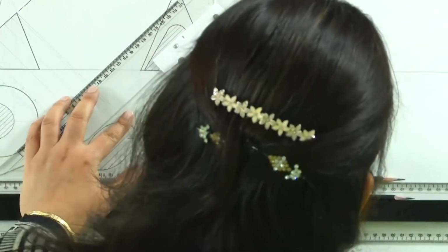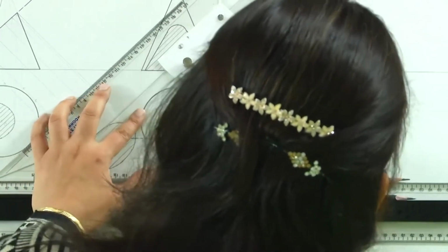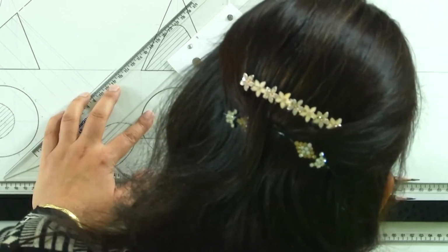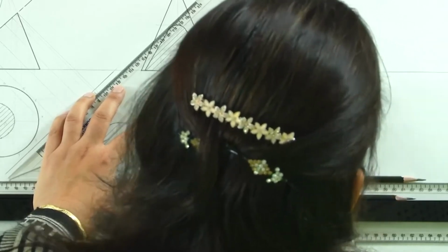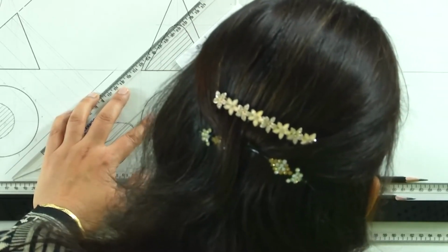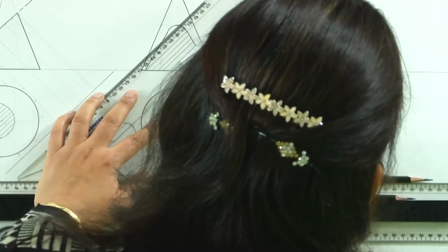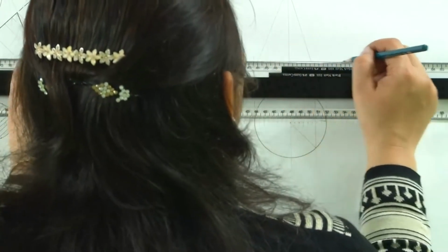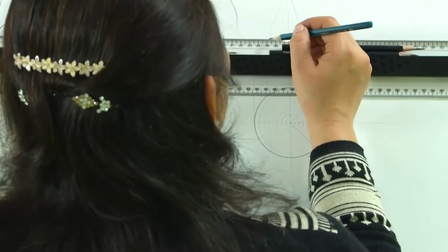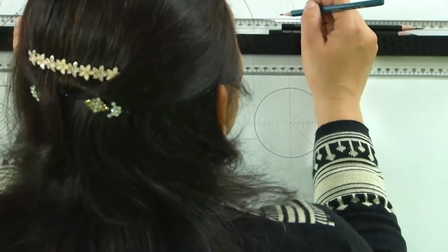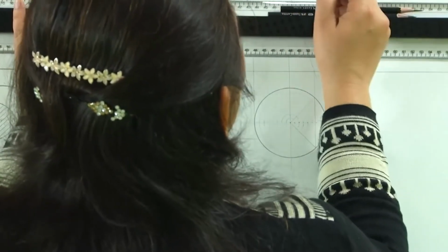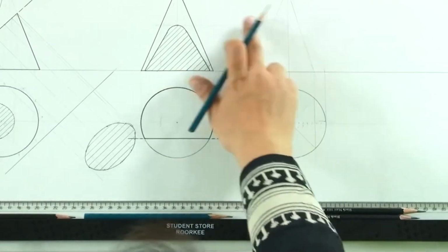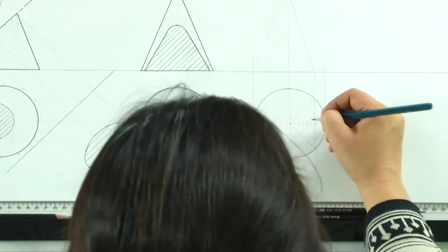So, what we are doing? We are going to take these projections up, and it is on this generator that each of the circles is going to pass, and that is where a plane parallel to the base plane will be passing. So, I will now draw these horizontal planes represented by these horizontal lines. These are the horizontal planes which are now intersecting in this.